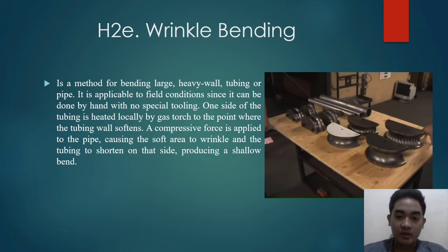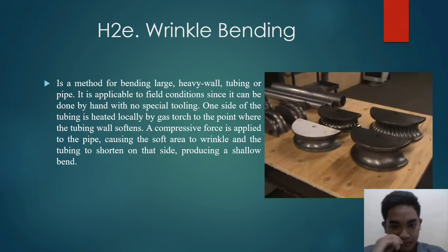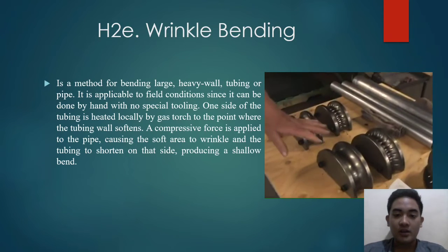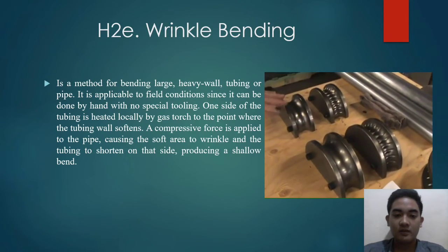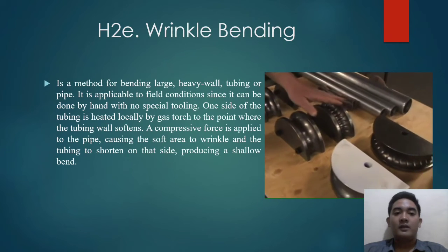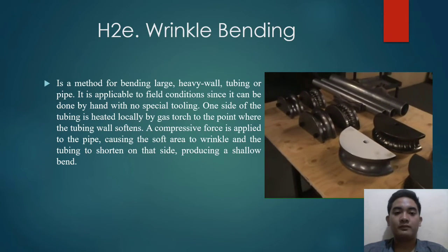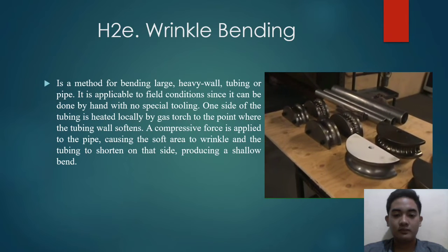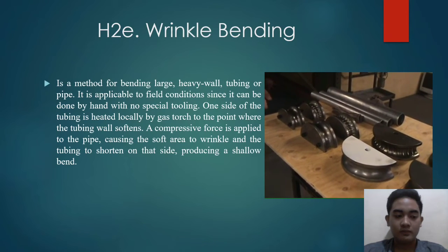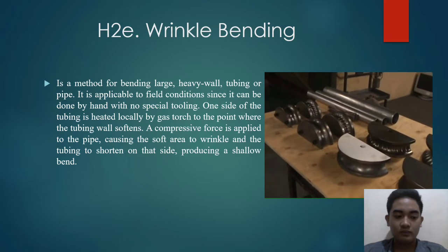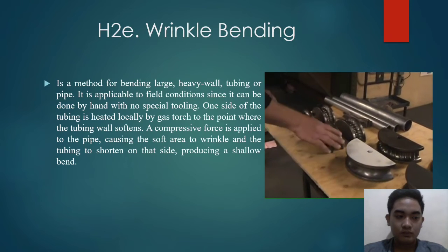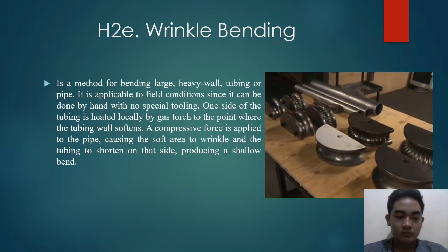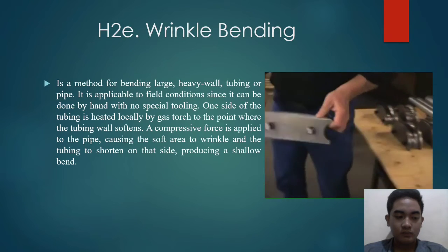All right, we want to take a minute here. We're going to talk and show bending on compression benders, the difference between traditional smooth radius dies and wrinkle control dies. The reason for a wrinkle control die is to bend a thinner wall material or harder material such as stainless steel. So we're going to start, we're going to bend with a 5-inch radius and we're going to work our way down into smaller radiuses. So we'll start with a traditional 5-inch compression die.